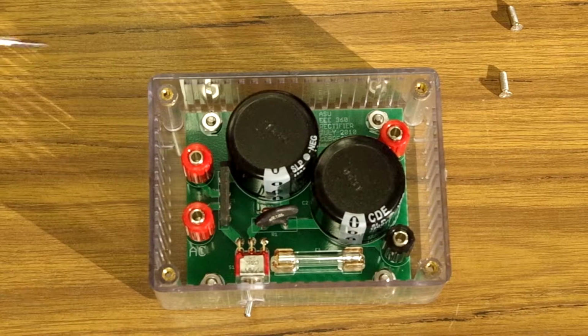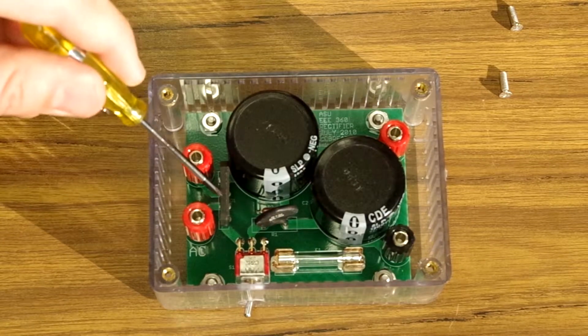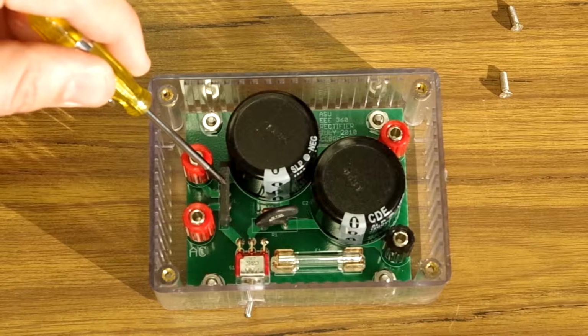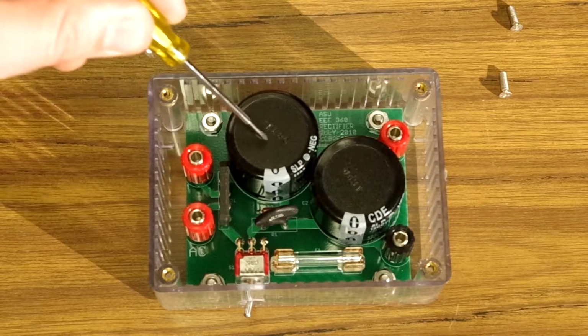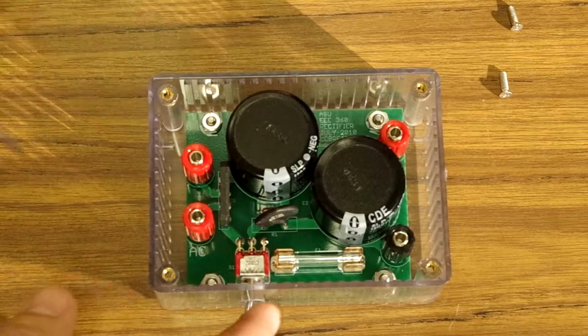And here's the inside of our rectifier module. Here are our AC inputs. This IC here has all 4 diodes inside. These are our 2 capacitors. These capacitors are connected in parallel to get the proper capacitance value.